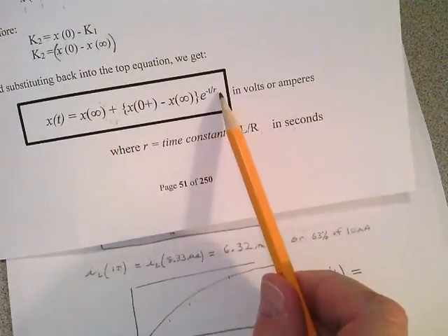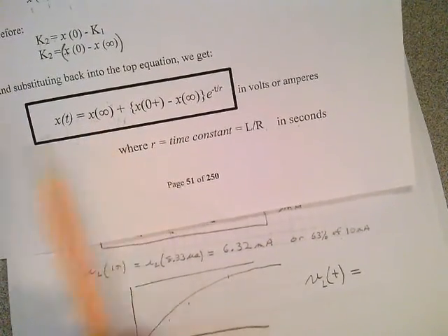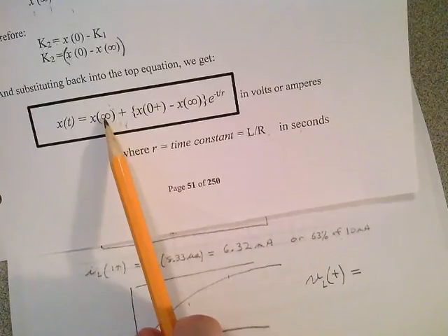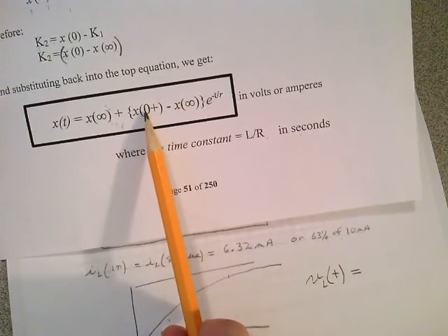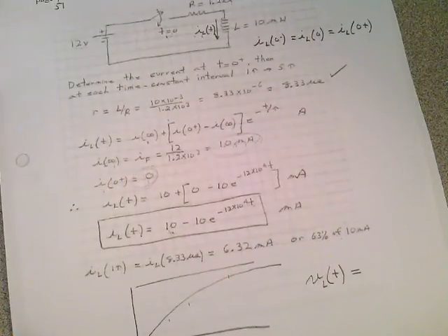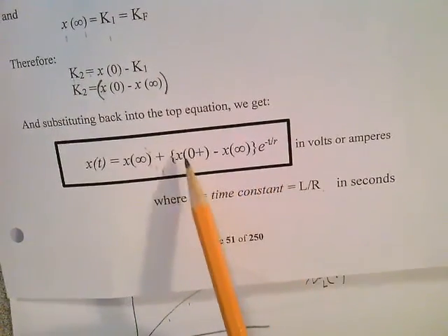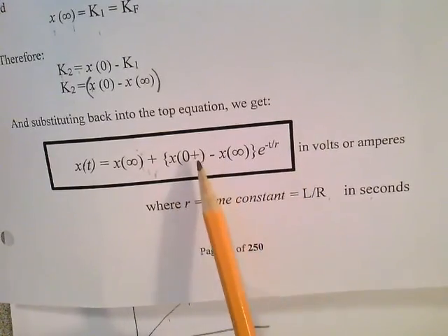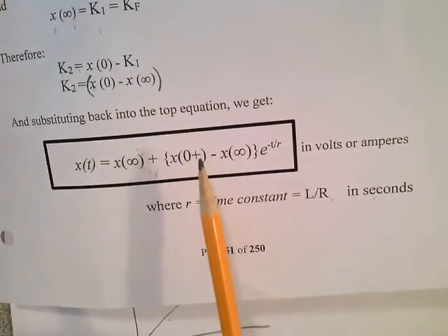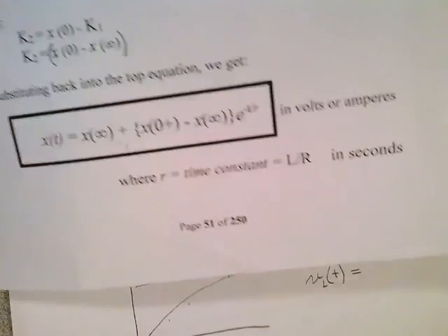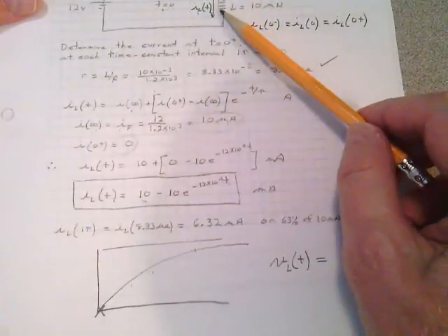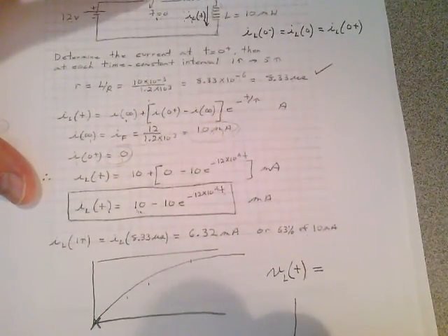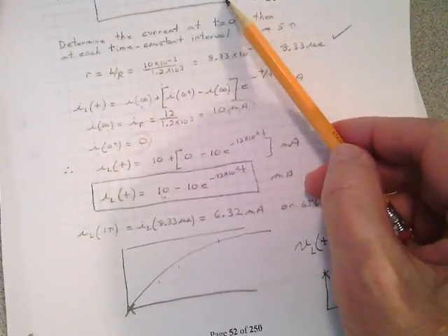Take your time, write this on a piece of paper, calculate the voltage at time equals infinity, then calculate the voltage at t equals 0, and put it into this equation. And see, once you put it into this equation, see if this value here cancels out with that value, and all you end up with is a decaying exponential. Because what should the voltage look like here? Well, initially it looks like an open circuit, so you're going to have a voltage there. And then as time goes on, that looks like a short circuit for voltage now.